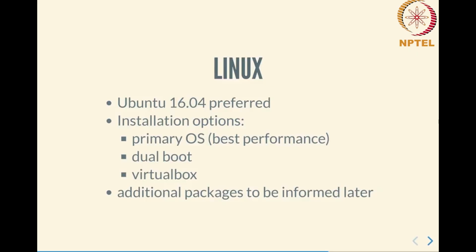Some other packages may need to be installed on Linux. These will be informed later as and when we get to them. Now, of course, you are free to install Vivado under Windows and use it. That is perfectly fine and works reasonably well. The only thing is we cannot support that in general. So if you run into any problems on installation or running certain tools, we will not be able to help you. The maximum installation that we have in labs around IITM is on Ubuntu 16.04. So that's the preferred version.